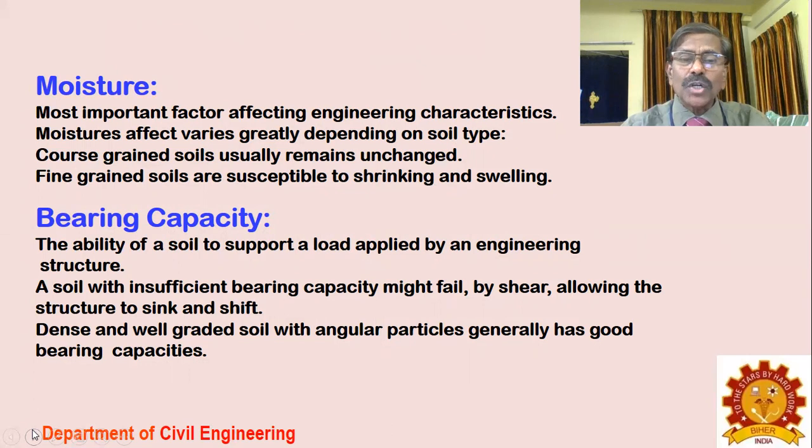Dense and well-graded soil with angular particles generally has good bearing capacities. Well-graded soil and angular particles have a good bearing capacity because well-graded means all particle sizes are uniformly distributed in the soil. So you can attain compaction very nicely, and a very reliable level you can get.